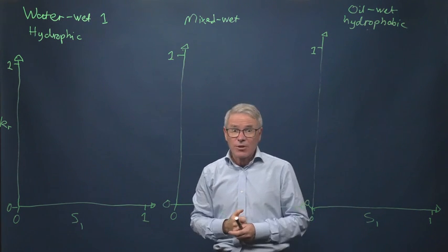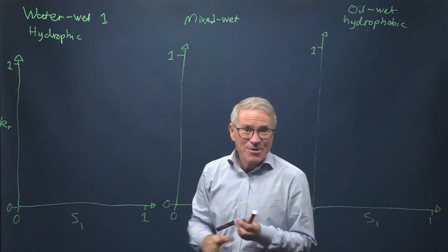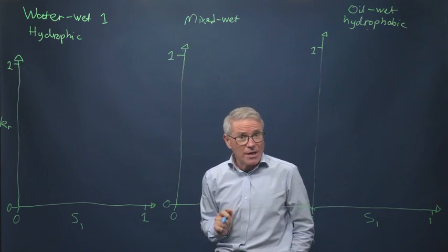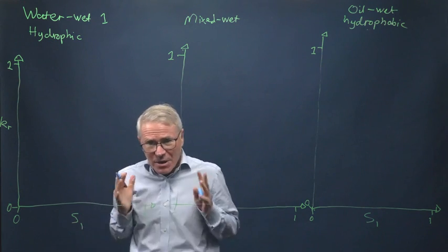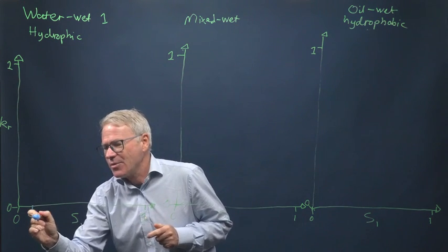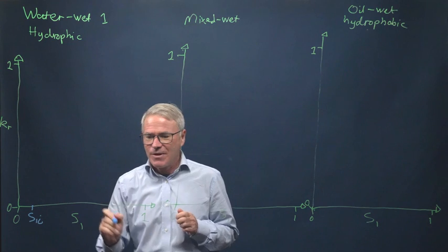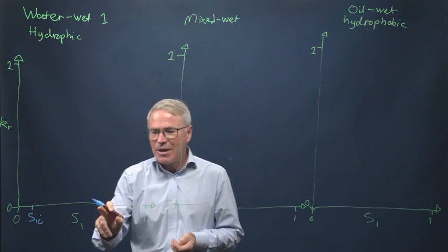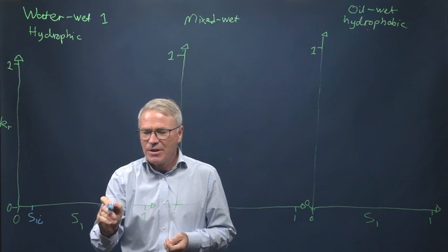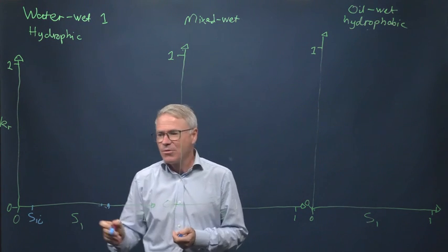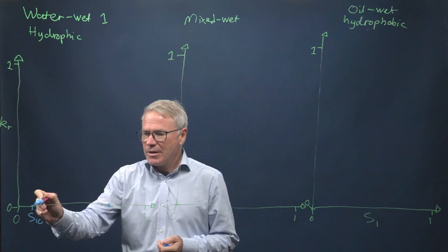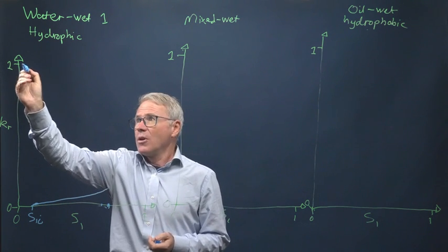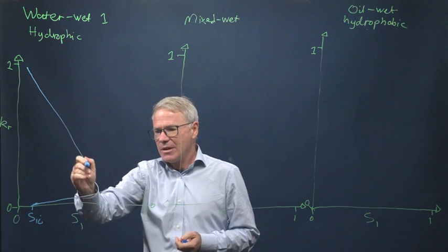Now I'm going to draw the functions. Now, we've already done the water wet case in the previous video, so I'm not going to dwell on it, but let's just go through it again because it's good for revision, and this is really key for the quantification of multi-phase flow in porous media. I'm going to actually take a case with really quite a high residual oil saturation. Here, 35-40%. Okay, and we have a water relative permeability that does this, and an oil or a gas relative permeability that, as I said, goes here.